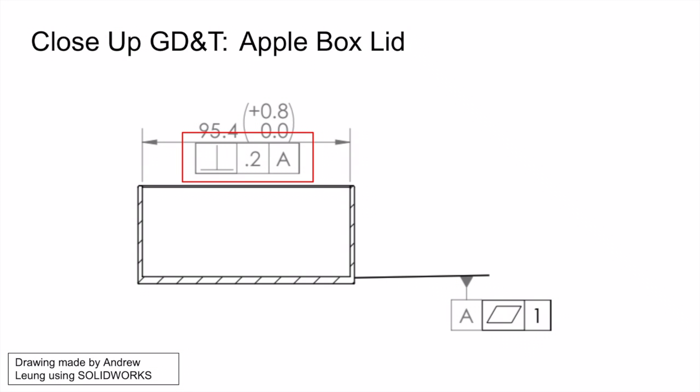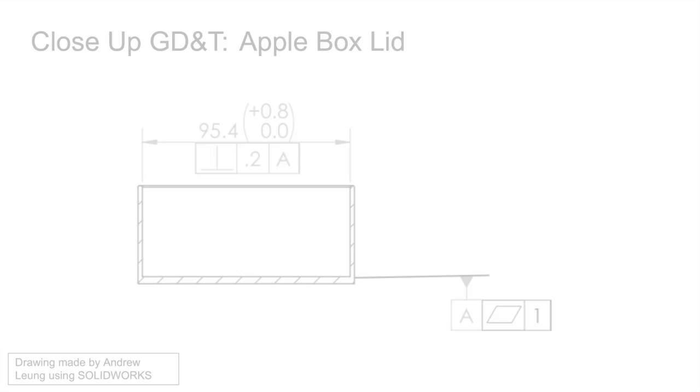The perpendicularity feature is the same as the base. A relatively small tolerance was chosen for both to tightly limit the amount of slant. Datum A is established to be the top face of the top lid. The flatness feature control is the same as the base.